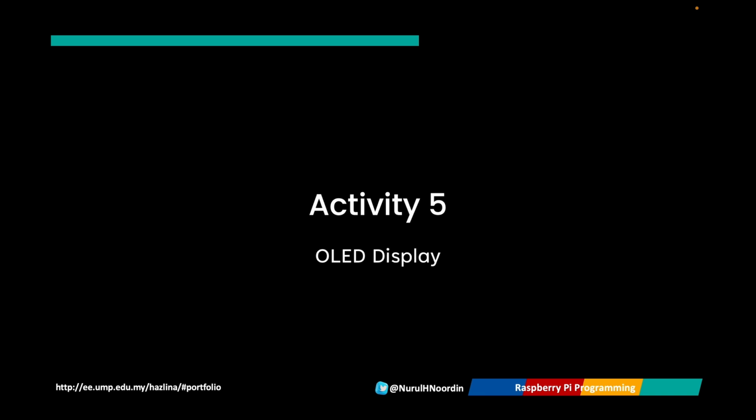Before we can use an OLED display with Raspberry Pi Pico, we need to install the SSD1306 library, which is specifically designed for I2C based OLED screens. This library provides functions to write text, draw shapes, and clear the screen easily. Here's how to install it.